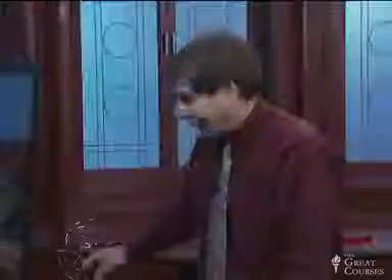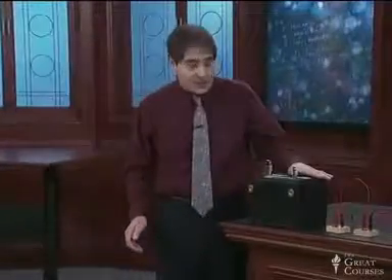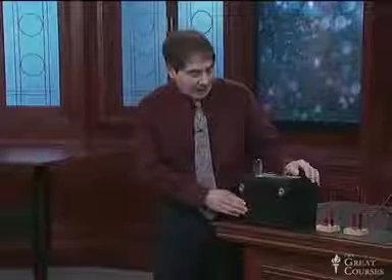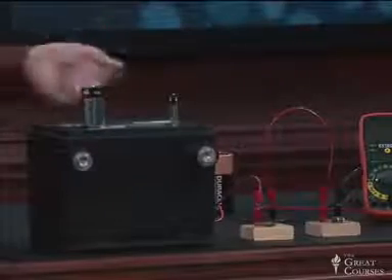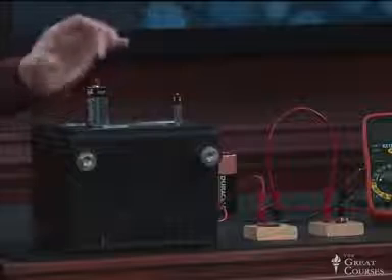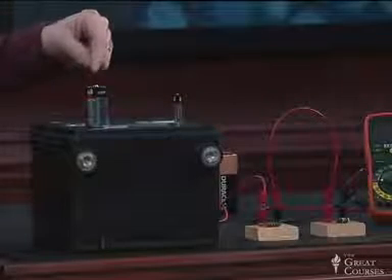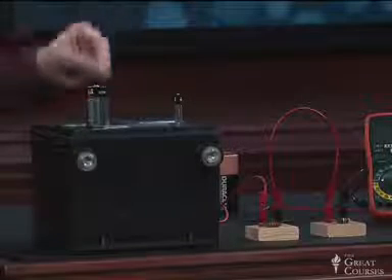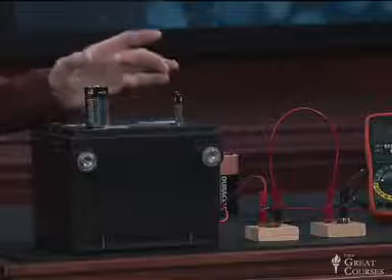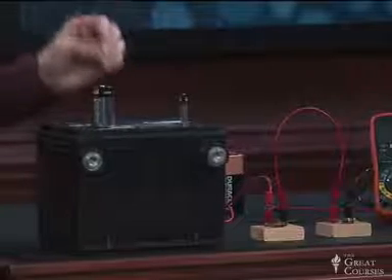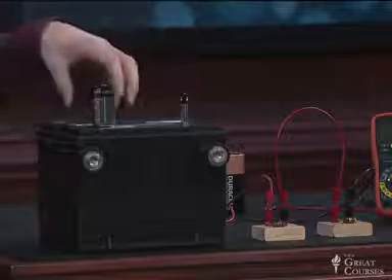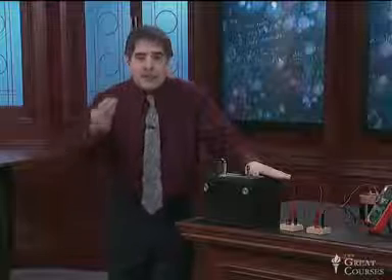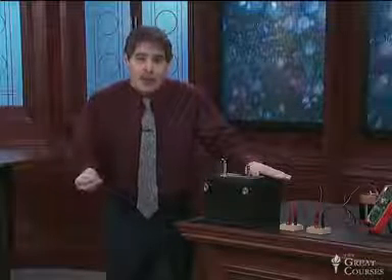So let's just take a second and look at some batteries. Over here, I have some batteries that we've worked with before. Here's our car battery. Here are two 1.5 volt batteries, a AAA and a D battery. What's different about the two batteries? Why does this one cost more? Why does this one last longer? Why can this one supply a more powerful flashlight with energy? Because it's got a lower internal resistance. They're both 1.5 volt batteries, but their internal resistance is different, and this one's internal resistance is lower than that one. The reason the car battery is so big and massive is because it has to supply 100 amps or so to run the starter motor of the car.